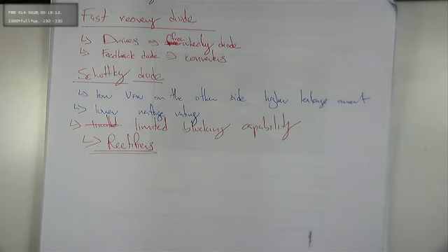How does a fuse act? It blows up before the device, because the fuse sees the current, di over dt, what is the current flowing at a particular time, all the time. So as soon as the current reaches above the rated value of the fuse, it blows up first, protecting your diode.